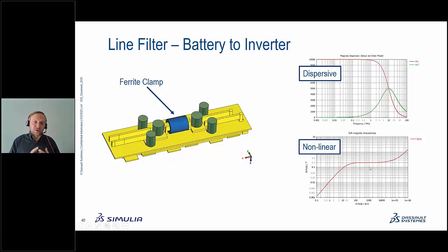The nonlinear curve gives you the effect that at higher field strengths the permeability is lower. And you loop this a few times until you get a distribution which no longer changes. And then you know that at certain currents only parts of your ferrite will be saturated. It's not a binary thing whether the ferrite is saturated or not.